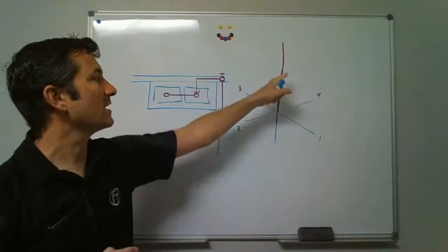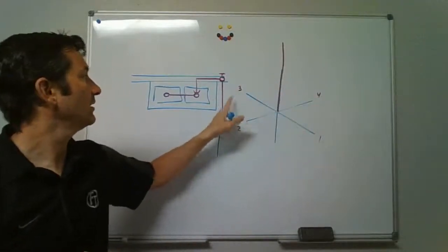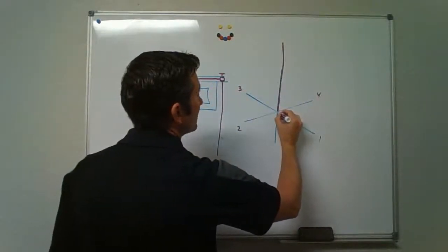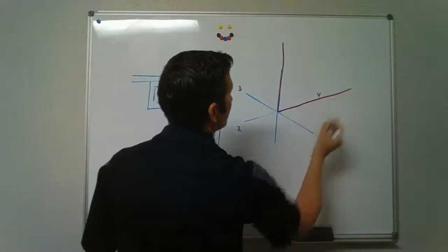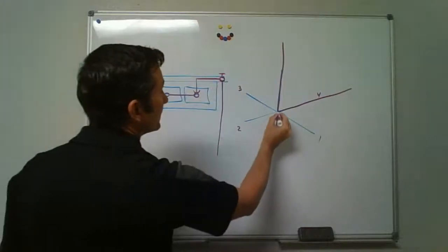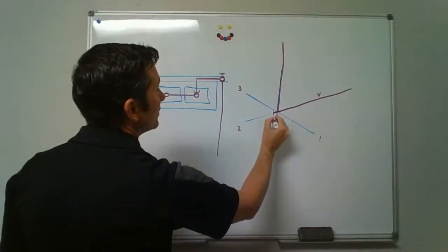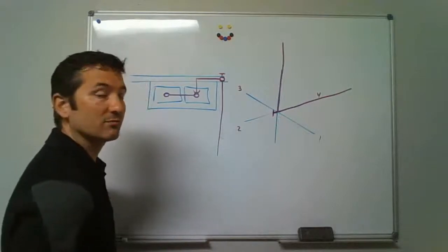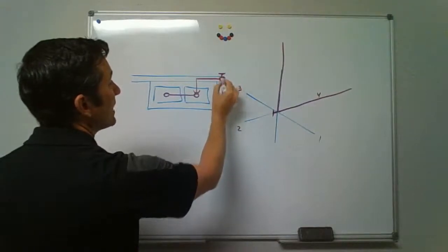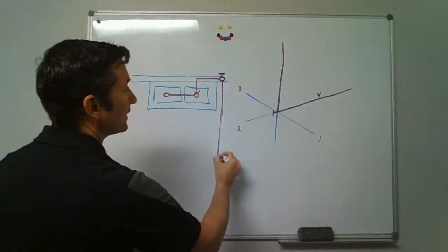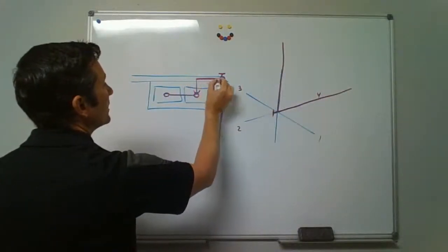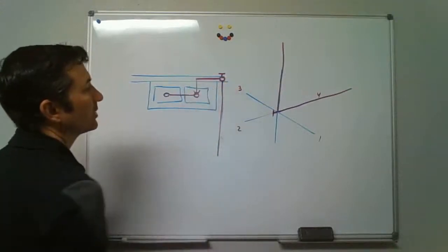Let's walk around to the back side and make it look like we're viewing the kitchen area from the back. So let's take this horizontal drain, but send it out towards angle number 4. Okay, so there it goes. We've got the symbol for the clean out in the back, so that's going to continue straight through with the vertical line straight up and down to represent the clean out. Now, we've drawn the vertical line, the clean out in the back, the horizontal drain line going out like this. Now we need to connect the T-fitting in the wall, arming over through the wall.